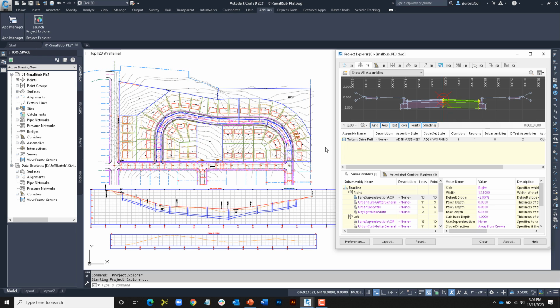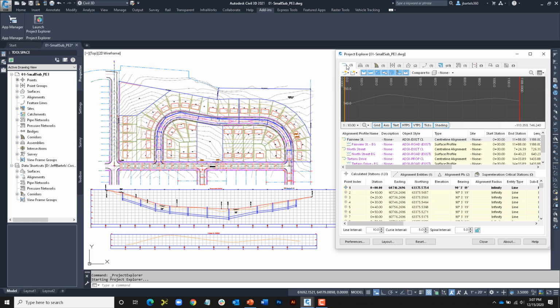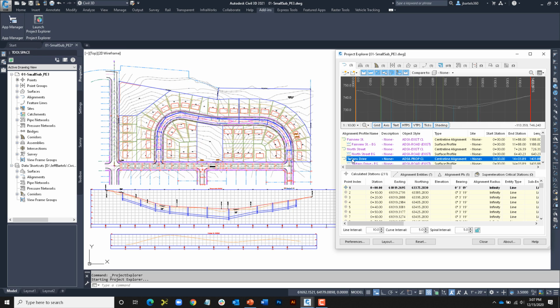Okay, I'd like to start this session where we left off. We talked about comparing data, so I'd like to compare a couple profiles. I'll do that by choosing the Alignments tab. Remember, the profiles live here as well. And I'm going to come down to the Object Data area, and I'll select the Tartan's Drive alignment. I will then tap my Control key so you can see where that alignment is on screen. Just beneath this alignment, we can see a pair of associated profiles.